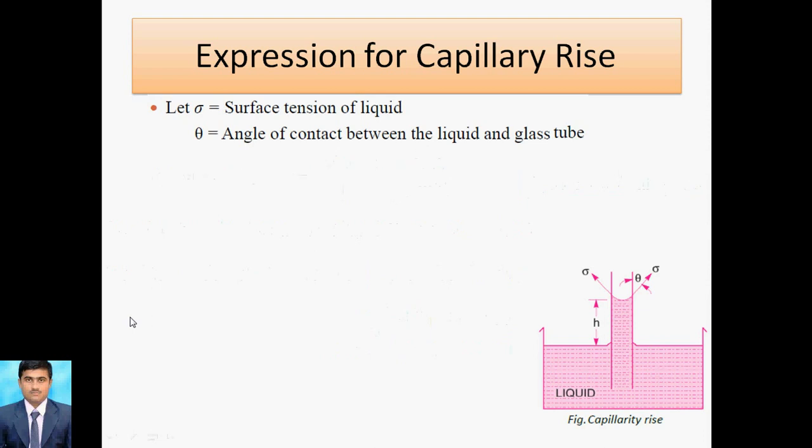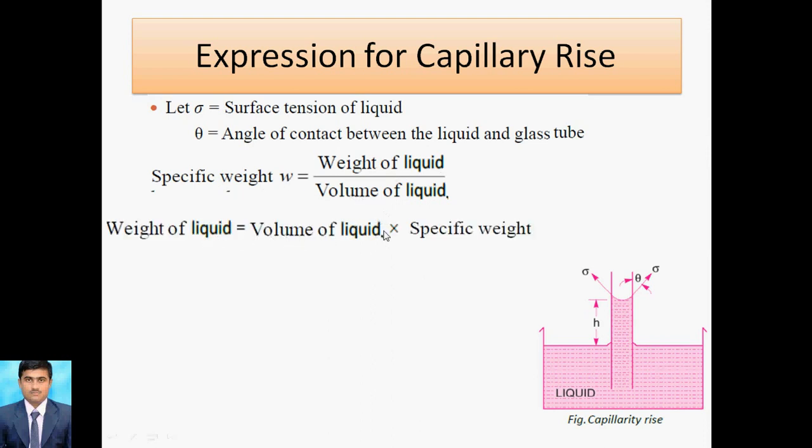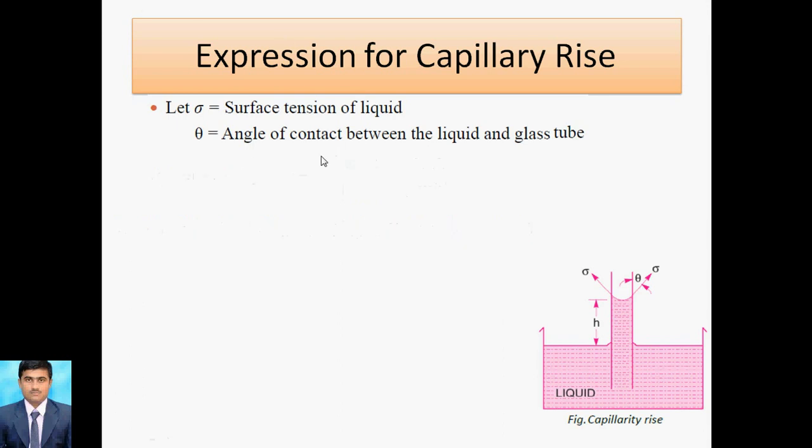Again I repeat, this effect is caused because of the weight of the fluid. The weight of the fluid is specific weight into volume. The capillary rise depends first on this phenomenon, the weight of the fluid.